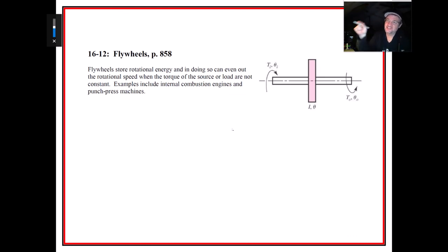To smooth out that really herky-jerky kind of load being placed onto the thing, you need a flywheel. And you remember the flywheel we passed around was a big old chunk of cast iron, and it needs to have a sufficient mass. You try to figure out, well, how do I figure out how much mass? Well, that's the discussion that's part of Shigley right here.